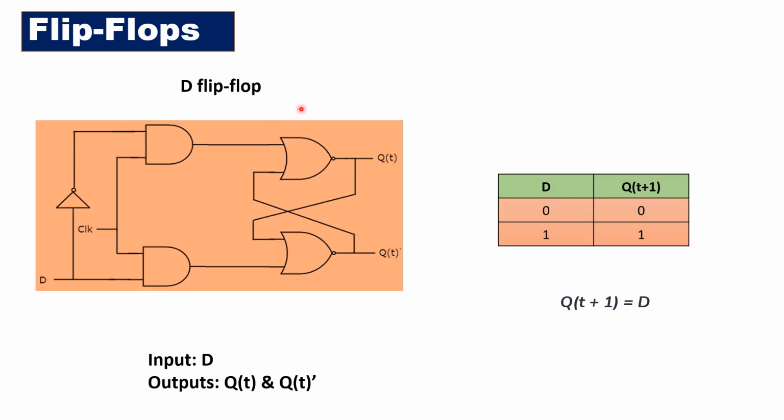The D flip-flop is a type of sequential logic circuit that stores and transfers data based on the timing of clock transitions. Here is a breakdown of how it operates. The D flip-flop only responds to either a positive or negative clock transition, meaning it is edge-triggered. This makes the output insensitive to changes in the input during the rest of the clock cycle, unlike the D latch, which is level sensitive and responds as long as the enable signal is active.